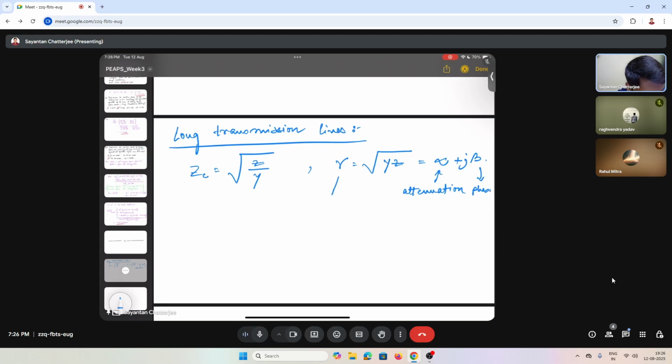And what is gamma known as? Phase constant? No, phase constant is beta, and gamma is equal to beta for a lossless line. So in those cases, we can consider gamma as phase constant because it bears the same value, but it has a different name.